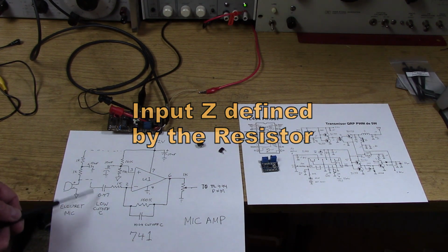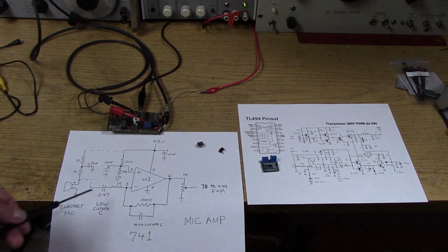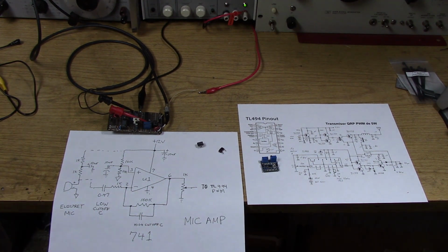Knowing that our source is fairly low impedance as well, we can calculate this capacitor and come up with a low cutoff frequency, and I found that a 0.47 or a 1 microfarad gets you well below the audio range, into the 30, 40, 50 hertz region. We can measure that and see where we ended up.